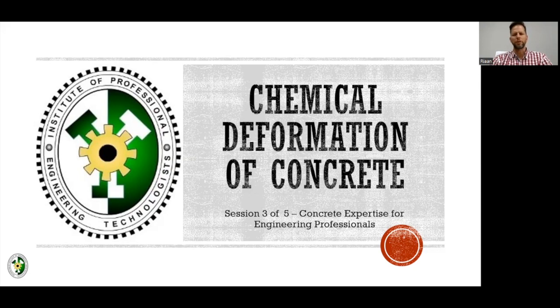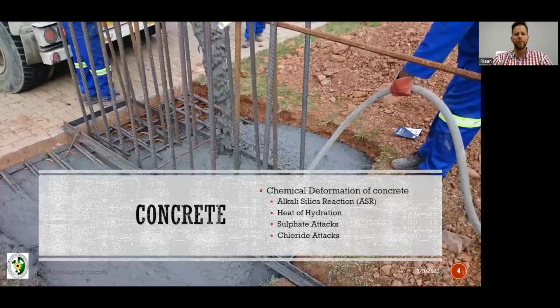In terms of physical deformation, the closest one in last week's presentation would be the carbonation shrinkage or the shrinkage aspects of concrete, even though that happens during its fresh state and also during its mature state. Chemical deformation, as we'd like to explain it, covers these four topics in very basic terms: your alkali-silica reaction, heat of hydration, sulfate attacks, and chloride attacks.